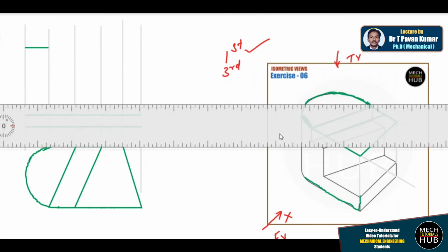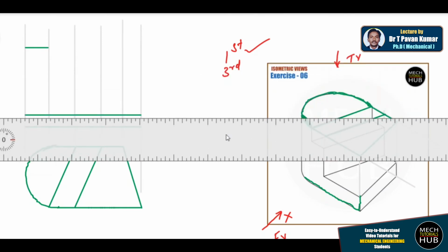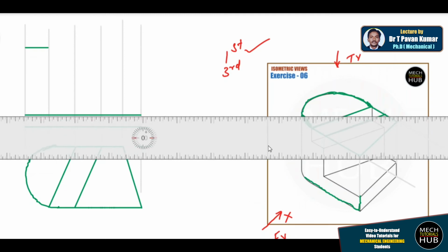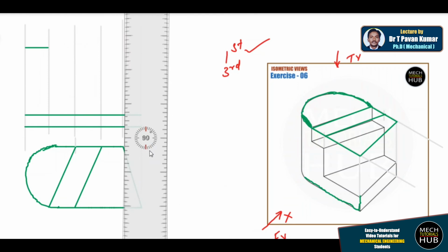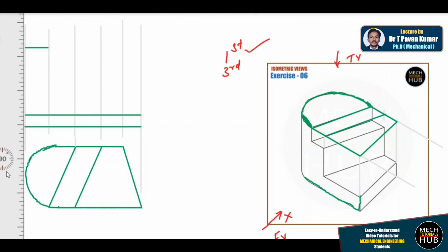Try to understand these 2 points which are important again. Okay, why we have drawn the projector lines or extension lines, you just need to understand now at least, because those are helping us to drop horizontals. Okay, from where to which point we need to draw, that is easy. Now this 110 mm I have drawn, and as I said in the beginning, this point is not at all coinciding with the point on the other side of the component.